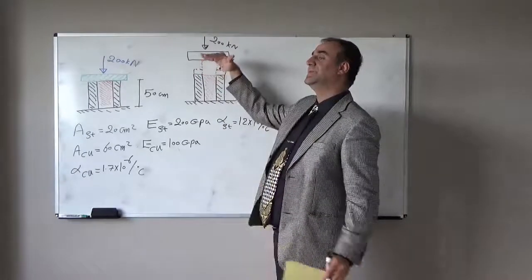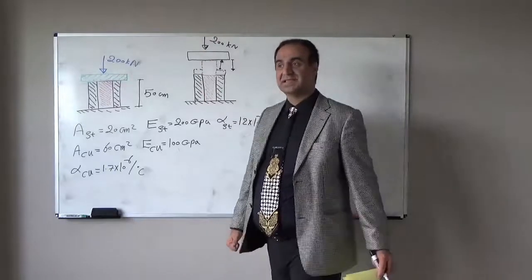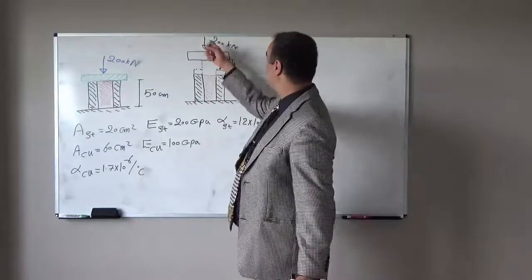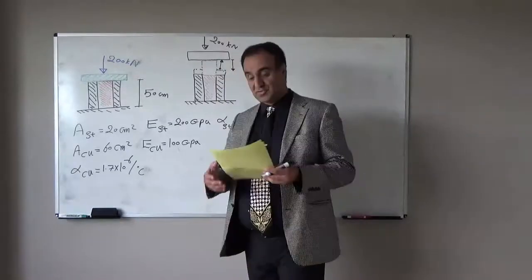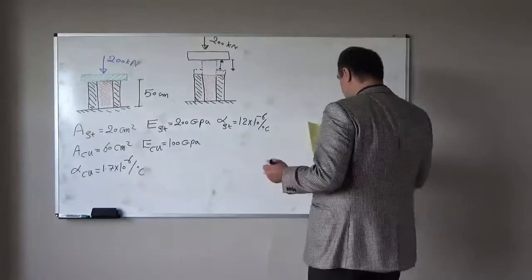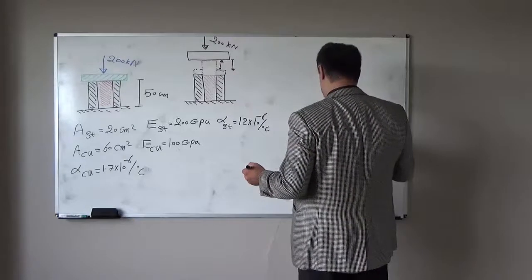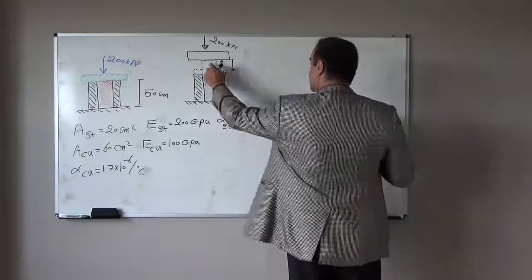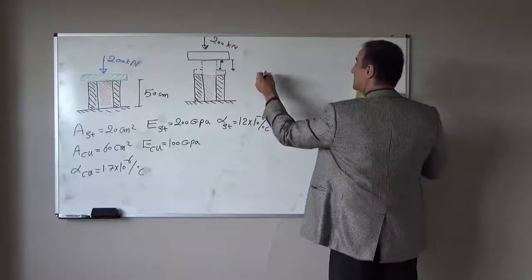After that, if we increase the load, both will deform. The problem statement says force will transfer only to the copper. So what we should do, let's look at the deformation of the copper under this load.